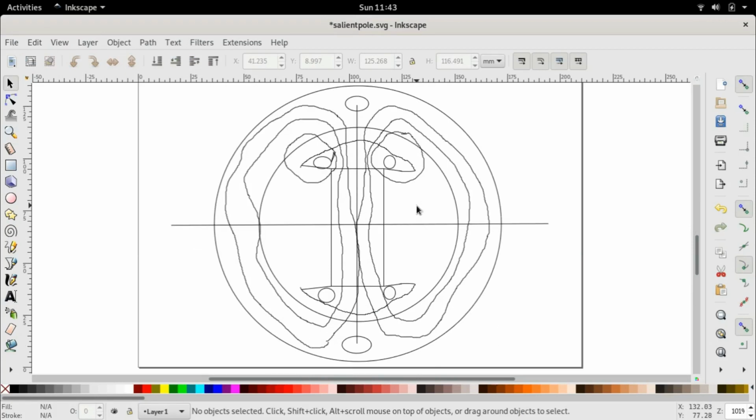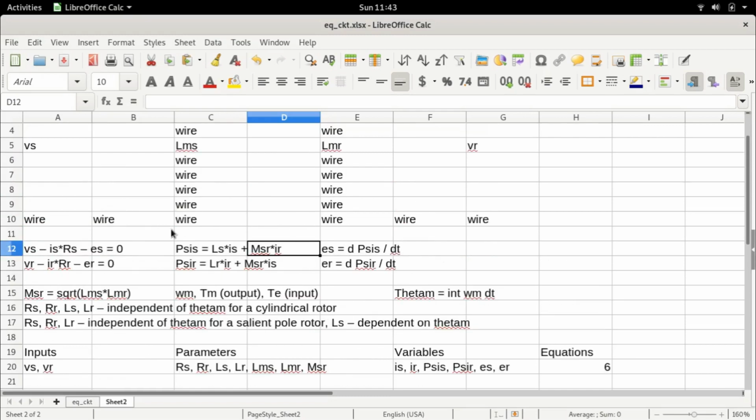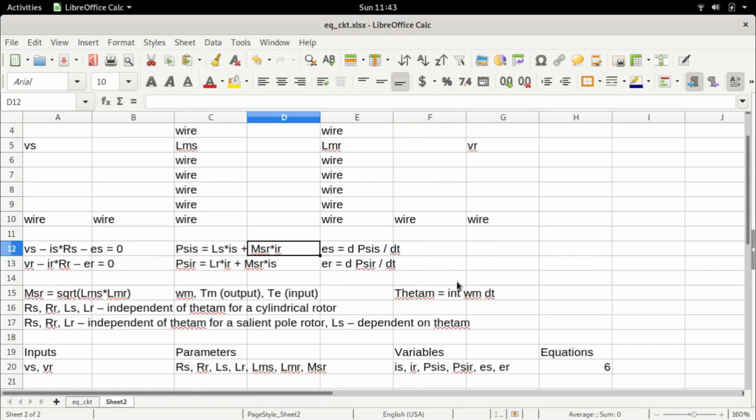So now that we have completed this, in the next lecture we will get back to our squirrel cage induction motor, and we'll talk about how the mutual inductance between the stator and the rotor is dependent on the rotor position angle, and we can also write an equation for how this mutual inductance is dependent on theta m, right? All this we will do in the next few lectures, but with this we have more or less decided most of the parameters. There's one last parameter remaining, and therefore we are fairly close to determining at least a basic mathematical model. The last step, of course, is to figure out how the torque will be produced because of the stator flux and the rotor flux, and this last part of determining the torque will again have us go back to basic physics and understanding how force is produced due to interaction of fluxes.